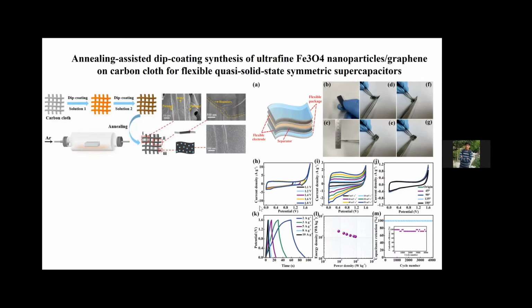And we know that for our supercapacitor, the first thing is the energy density, half C V square. V means the voltage window. So if the voltage window is increased, we can see it is a square form, so higher energy density can be achieved.